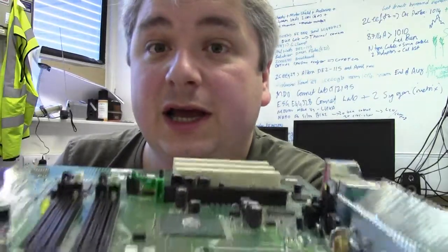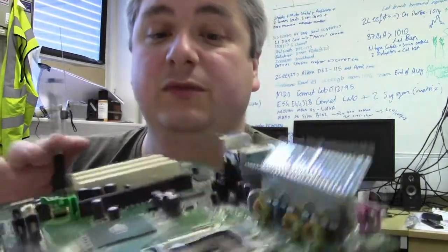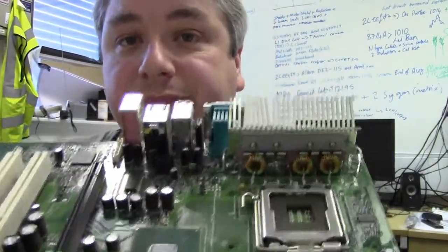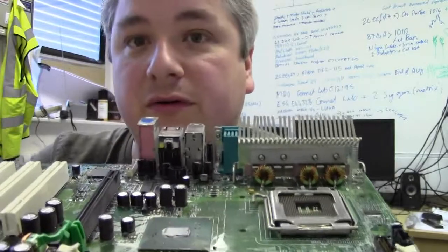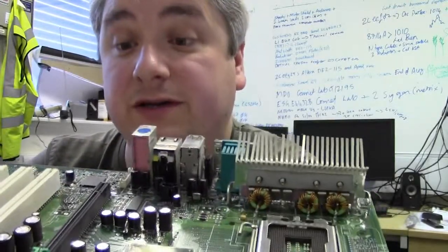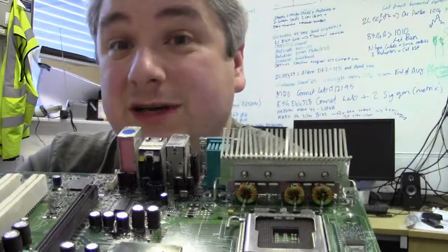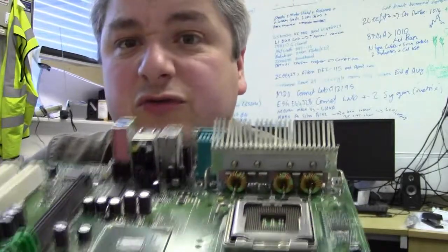With electrolytics, it's quite easy because they are proportional to the size of what they are. So if it's quite a wide cap, it's going to be quite a high value of capacitance. You can try and match it up with other ones on the board. If it's a board like this motherboard, then generally those particular widths of capacitors or heights will all be the same value, and usually grouped around in the same areas.